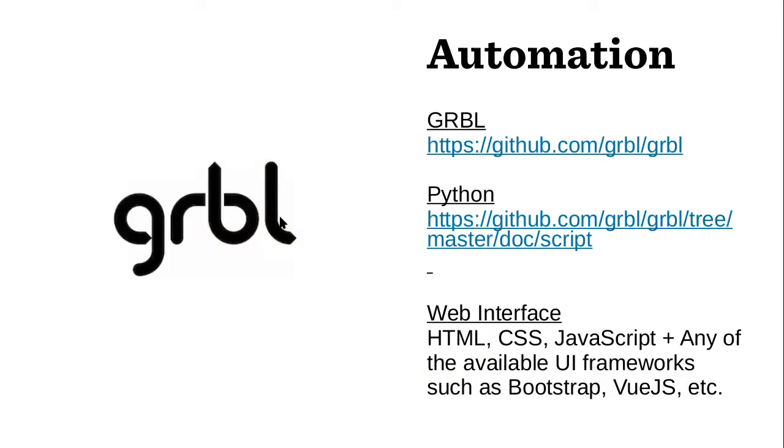And then for the automation part, these boards use GRBL. As for the stepper shield, Arduino is the base, and then you install the GRBL interpreter on it, which makes it appear as a serial device on the computer. Then you can use this serial connection to send GRBL messages to the Arduino, which are translated into the motion of the motors. You can find more information about GRBL over here.